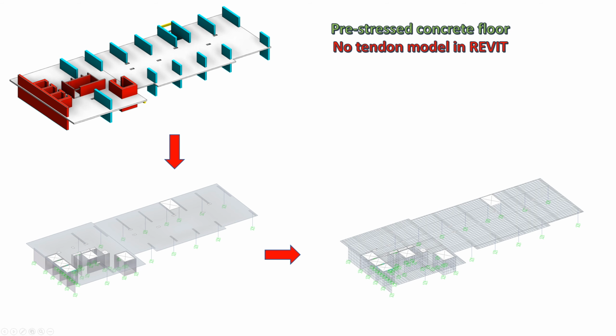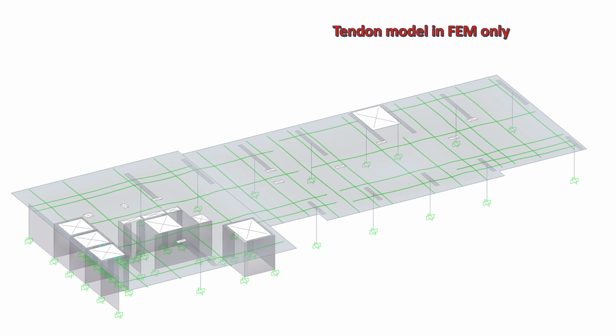For the pre-stressed concrete floor, currently, I personally did not have success with transitioning tendon models in Revit into finite element model. Therefore, what I do at the moment is creating a tendon model directly in the finite element model.